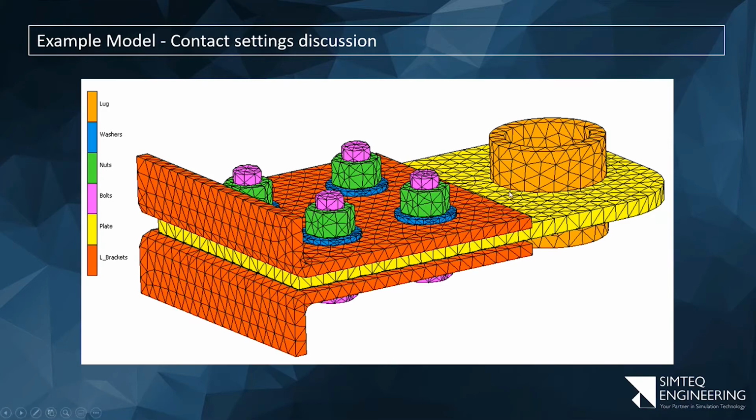Ideally, I'd like to remesh this because I want to make contact from the green part of the nut to the washer, simply because the nose there on the outline exactly determines where the interface or the outside edges of that section is. It's not going to make a massive difference, to be honest, unless I've got a really coarse mesh on both of these sections. What about this section, the bolt itself, that shank section, and the nut, or the threaded section in there? I'm not modeling the thread. I'm probably going to use glued contact between the two.